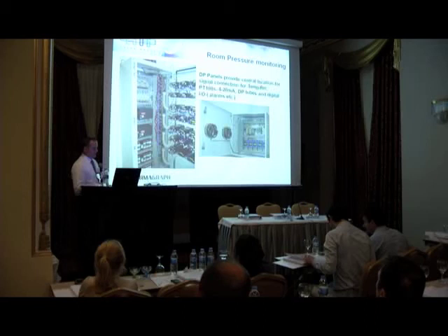And here, if any of these are flashing, that means it's unacknowledged. So typically you expect to see something red and flashing that's gone into alarm and it hasn't been acknowledged. But you could come in the morning and see something flashing green. And what that's telling you is your system's healthy now, but in the night time, maybe one of your pressures failed because your EMS system has failed or something like that during the night. It's just telling you you've had a problem.